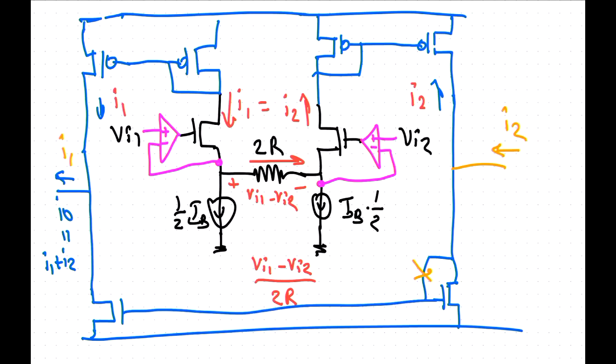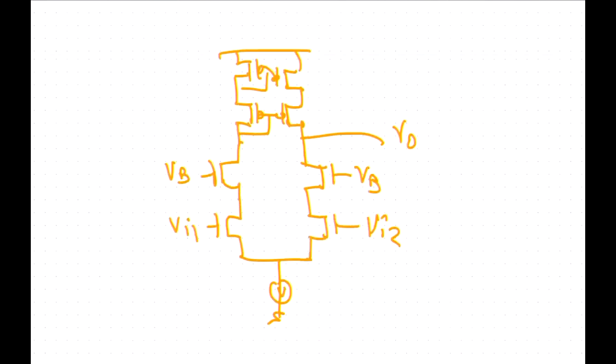The power draw would be quite a bit more, because you have to add the amplifiers. So these amplifiers are not complicated. If you can get away with it, this would be an amplifier of this type, but probably without the cascodes. Yeah, so just a differential pair with a current load.